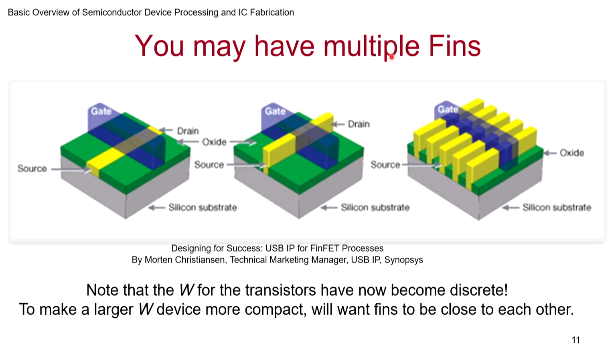So it's like having multiple transistors which are put in parallel. So you have transistor 1, 2, 3, it behaves like that with a common gate, and of course you can have a common contact, as we will see in one small figure that I have later. So if I want to make larger W, I just need to have more fins.